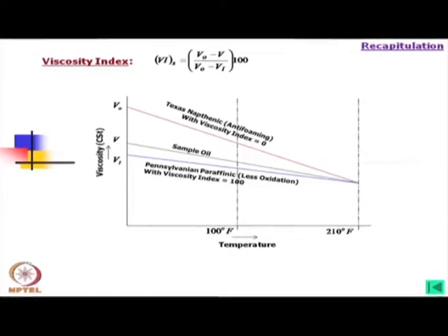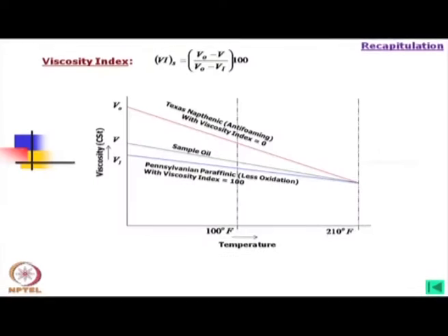However, one important thing is the viscosity index. While selecting any fluid, we should know not only the viscosity but also the viscosity index, and the range depends on that. You may find the viscosity of an oil is very good, but it has a poor viscosity index.